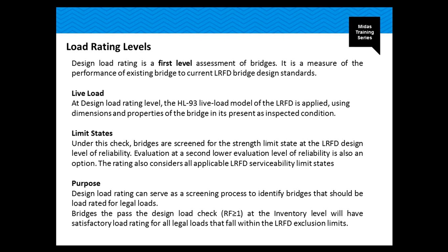In this case, the bridges that pass the design check, which is the design load check, with a rating factor higher than 1 at the inventory level, have a satisfactory load rating for all legal loads that fall within the LRFD exclusion limits. So it's basically applying the LRFD standards to the load rating using the HL93.